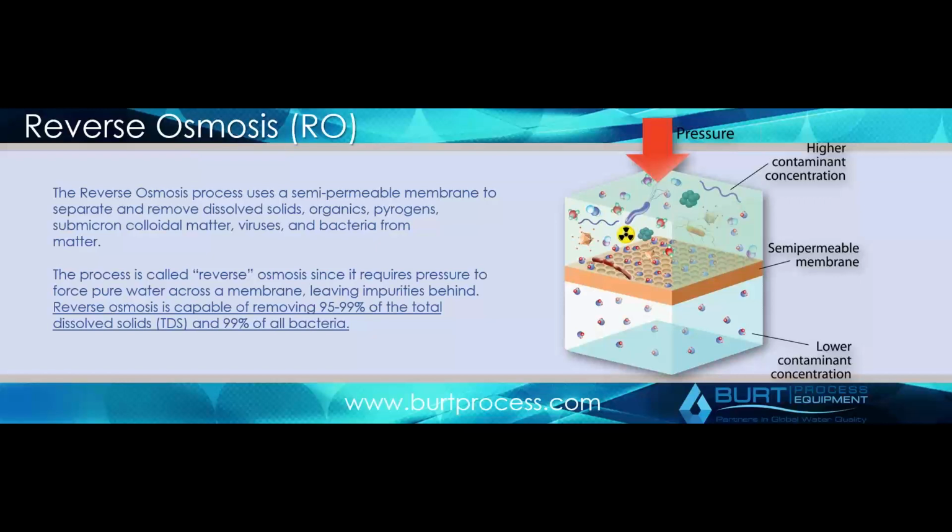So if you go back to that chart I showed at the beginning where you're talking about water quality, all of those different items, the majority of them are some form of dissolved solid. That's why the RO is so critical. It's going to get you 95 to 98% of the way there just by having a high efficiency RO. And then every process that comes after that moves you to that final step of getting you to that target water quality that you actually need.